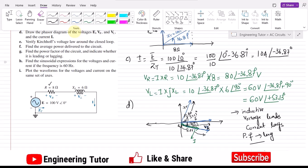Now moving forward, in part E of our question, we have to verify Kirchhoff's voltage law across the closed loop. According to Kirchhoff's law, let me write it here: E is equal to VR plus VL. What is the value of VR? The value of VR is already known, and that is 80 at minus 36.87 degrees, and the value of V of L is 60, and the angle it has is 53.13 degrees.